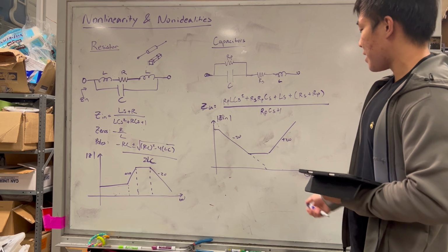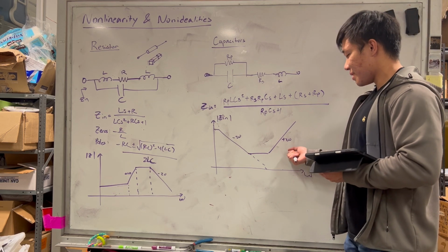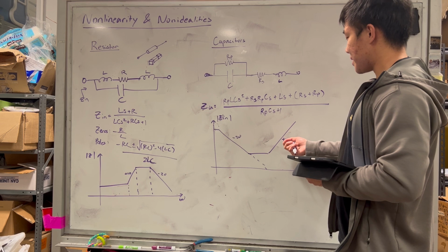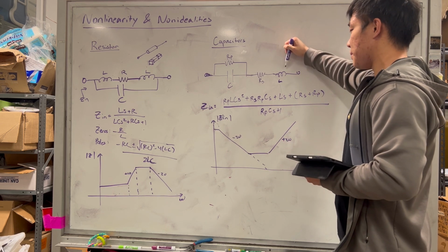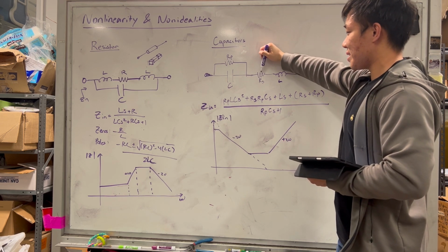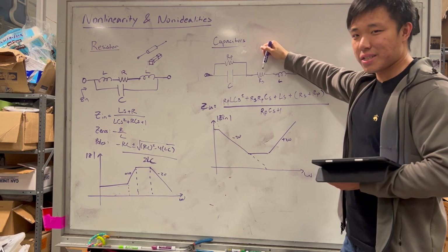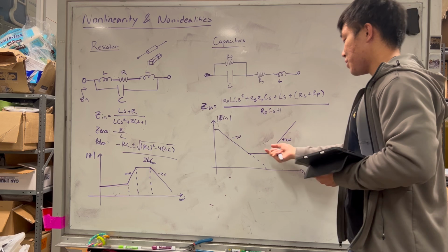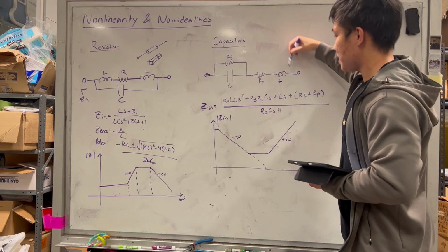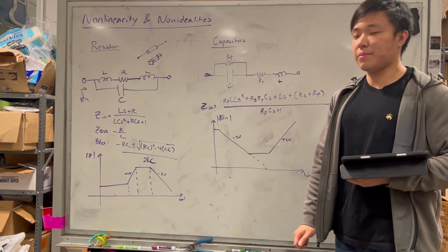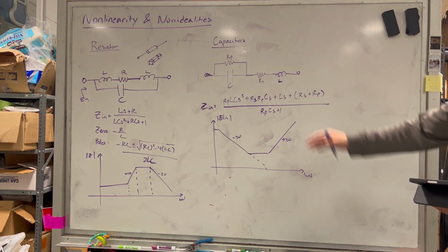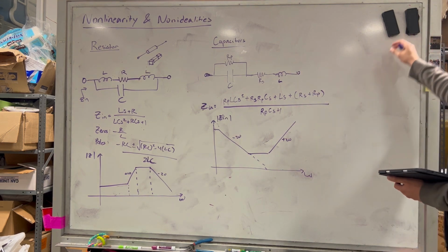But you'll notice that at super high frequencies, sometimes it's not purely just going to be the inductor that's overwhelming it. The ESR is not a purely linear component. This resistance actually changes as well. But at super high frequencies, these tend to dominate, and you won't actually see the capacitor that much anymore. So that's your capacitors, right?